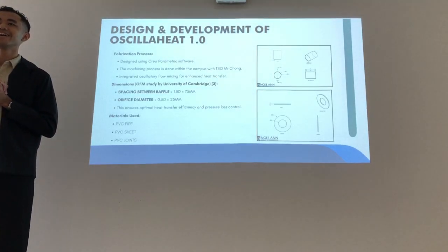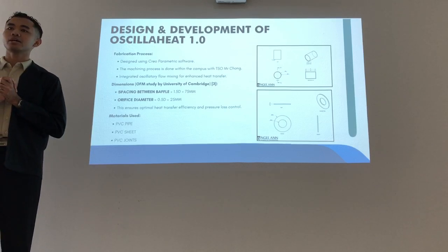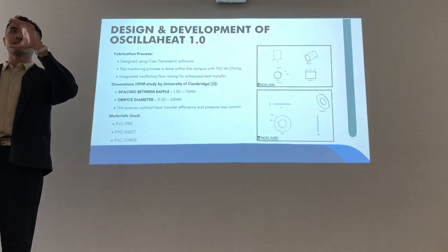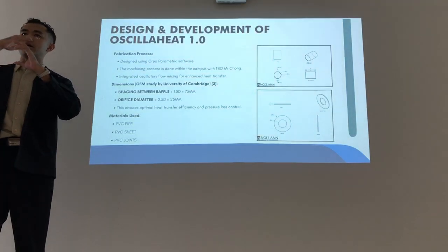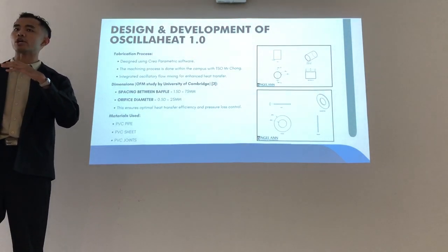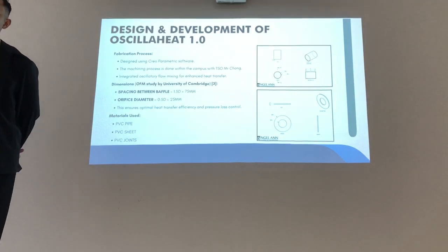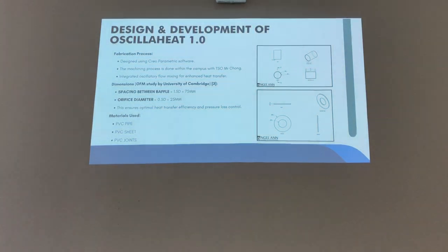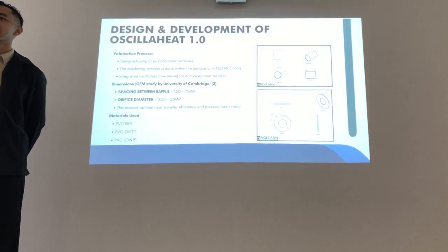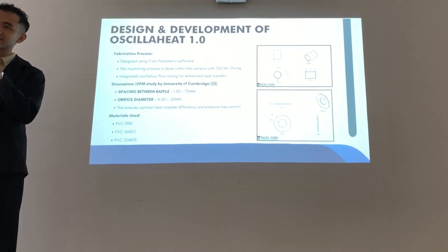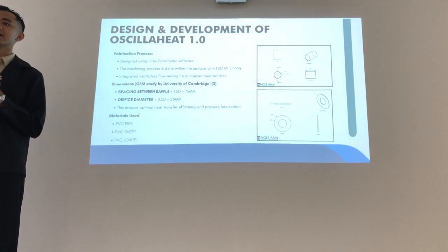I thought there would be two sizes so that you can force the flow to go up and down, one attached to the outer pipe and another attached to the inner pipe. Correct. That was another study, that maybe we can do a different design, with two different baffles inside the system, to make the flow different or increase the heat transfer. But we haven't tried it out to test whether it works or not. If you were to attach a baffle to the copper pipe, you can have a copper baffle because it can be brazed on. Whereas it is very hard to attach something to the plastic pipe. I don't know how you're going to weld it there. Can you weld PVC or not? Currently there's a plastic weld, but that is for plastic purposes. But to put the copper inside the pipe, I don't know how far you can reach there because of the diameter of the pipe.